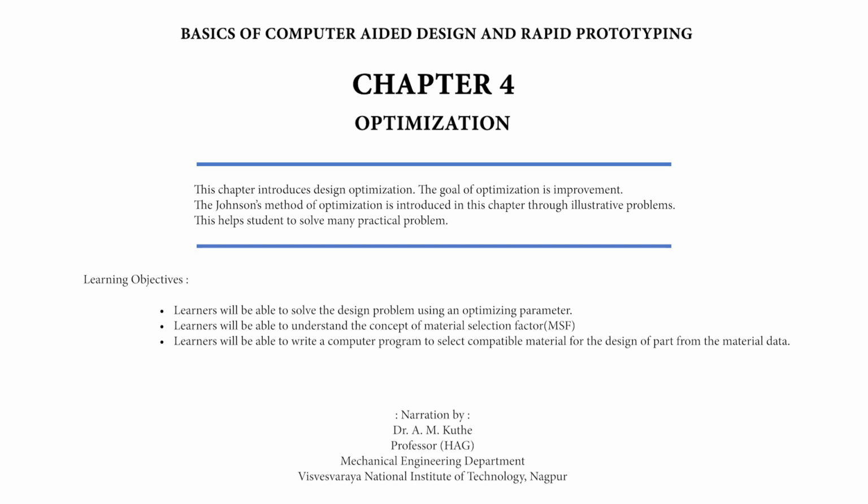Number 2. To identify the variables. Functional: F, Fs. Limiting variables: SB, D, L. Free variables: M, Z, I. Number 3. To decide the type of the problem. Number of free variables NF is equal to 3. Number of subsidiary design equations is 4. As the number of free variables is less than the number of subsidiary design equations, the problem is a redundant specification problem.